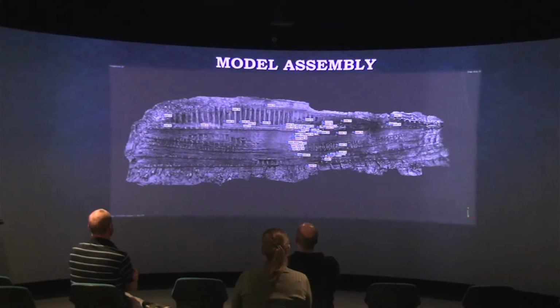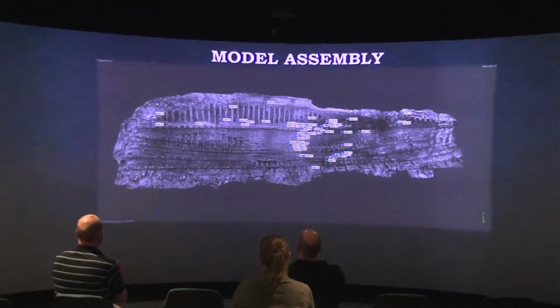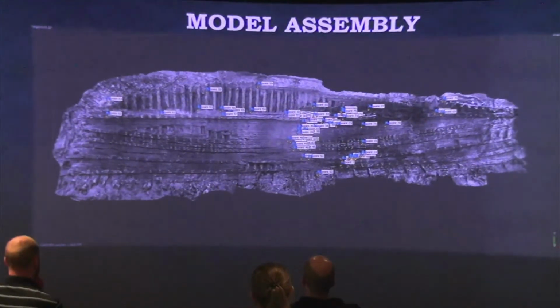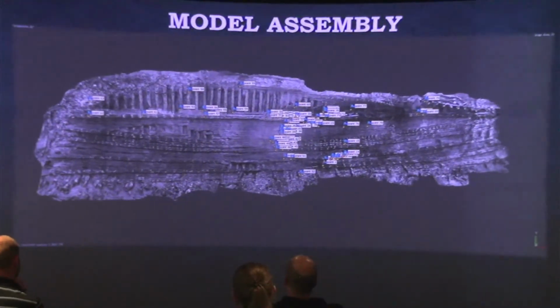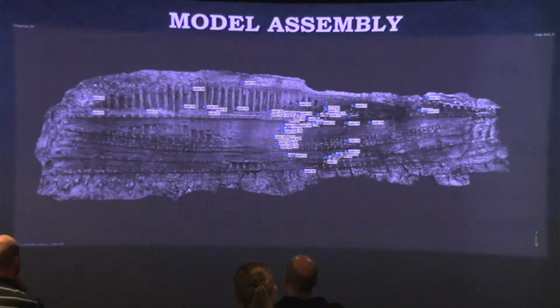So around 80 control points, also known as markers in Metashape, were used in most of the 603 images that I had access to act as a guide for the bundle adjustment algorithm. These markers were primarily placed on the corners of ship's planks, patterns and cracks in the wood, and even seashells.